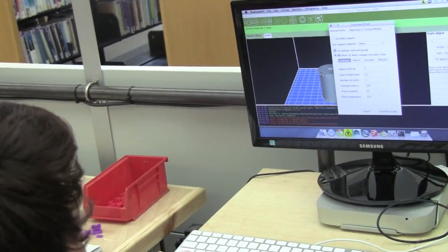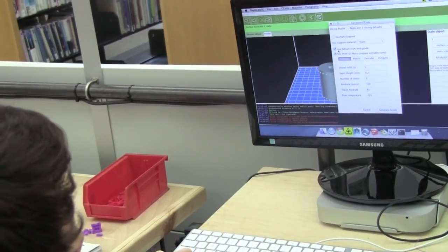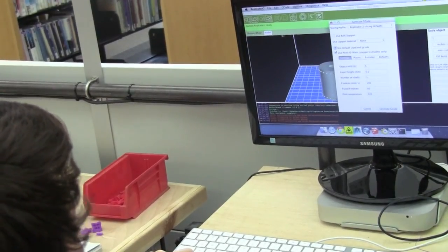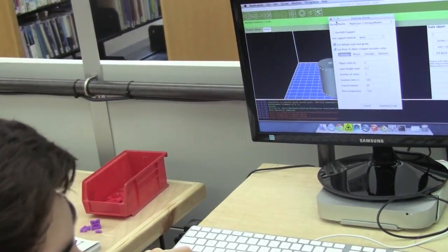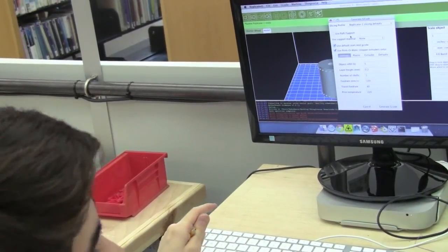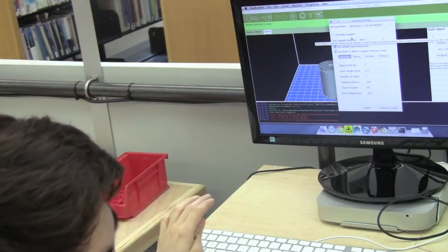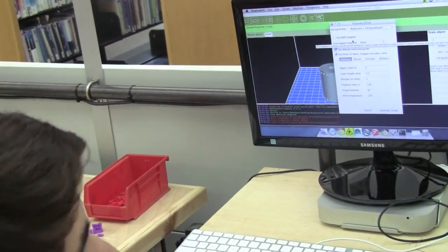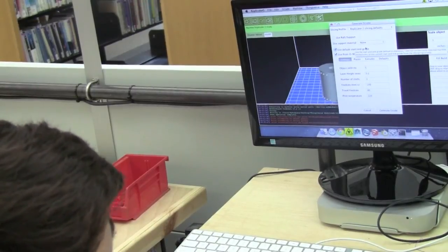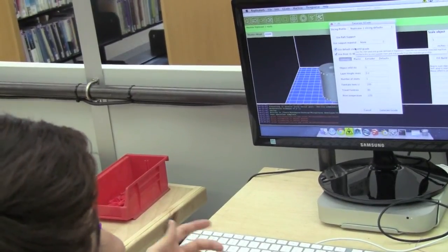Next are these 2 boxes. You always want to keep them checked, and I'll just explain what they are briefly. G-code, although I don't have any generated right now, is, like I said, all those coordinates, but also at the beginning of every print, there are commands that say run safety checks or heat the extruder, stuff like that. That's what's automatically generated by default. If you were to not check that box, then it wouldn't be generated.